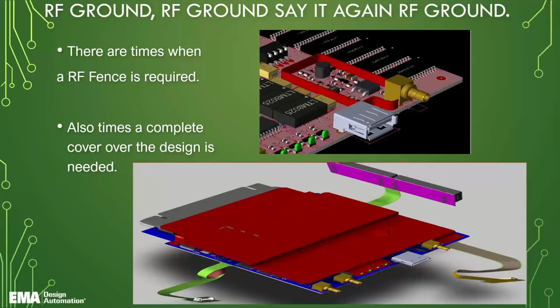There are times when an RF fence is required. We're isolating RF signals within the entire RF design, and we'll do that either with a fence or we'll do a complete frame chassis that would set over the board and bolt down onto the board. That fencing or that frame is going to have an isolation in there. We create what we call mouse holes that let the signal leave that area, and that's a controlled signal going to another section of the RF board. And there are times where we do a complete cover over the design, a metal frame. Some applications will do conformal coating, but in most cases, the metal shield is the best.